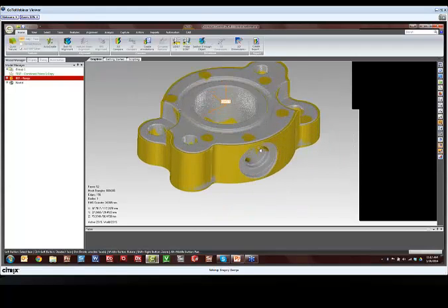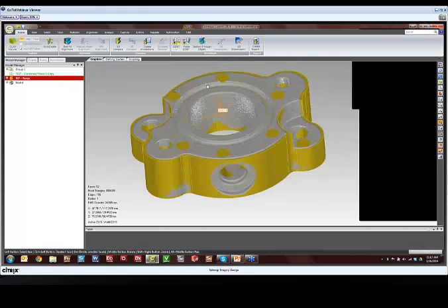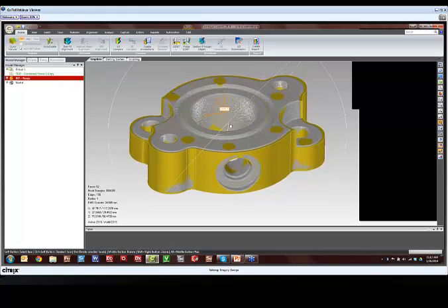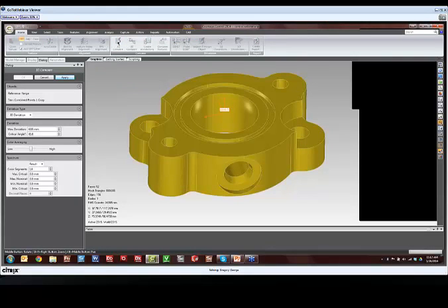So you can see now that they're on top of each other. The first thing I'm going to do, if I have all of these measurements in 3D space aligned to the CAD object, one of the most popular things to do is just to create a 3D comparison between the CAD model and those points.